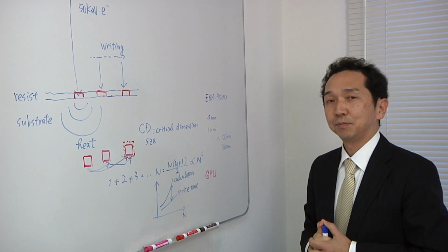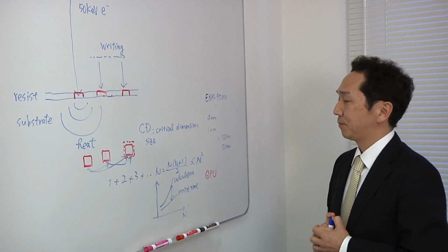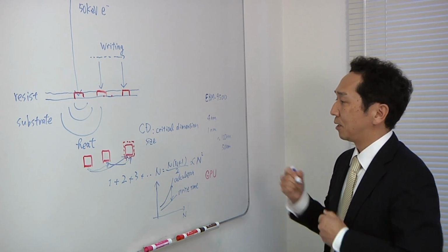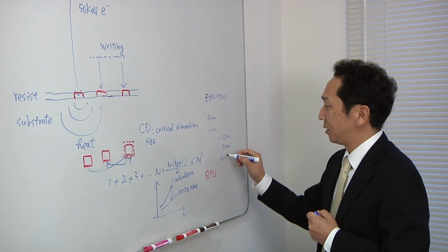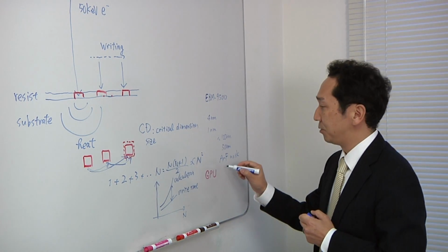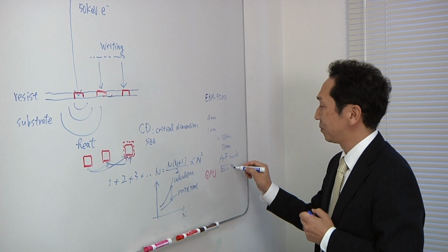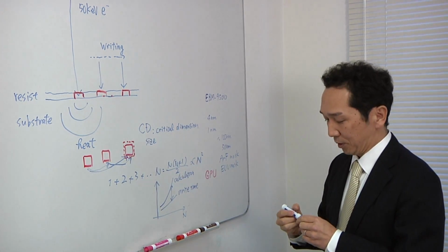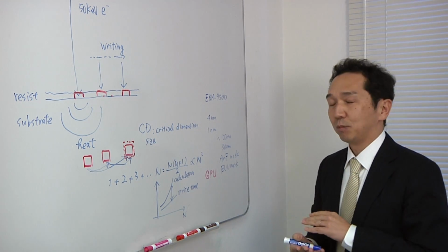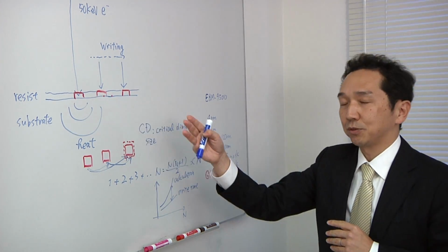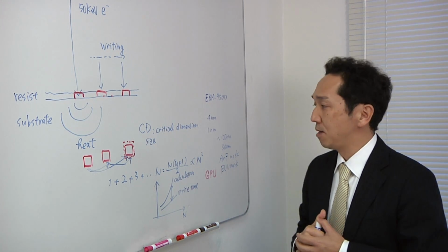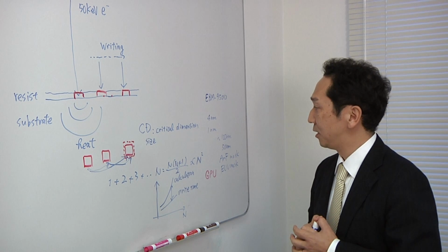That's our next task. Does the lithography source matter at all here? Are there multiple options? That's one thing we have to test in future. We are testing ARF masks now, and we don't have much data with EUV mask yet. But that's a good point. The EUV mask has thick metal layer compared to ARF mask, so the heat dissipation, diffusion coefficient may be different from that of ARF mask. So that's one thing interested in testing in future.